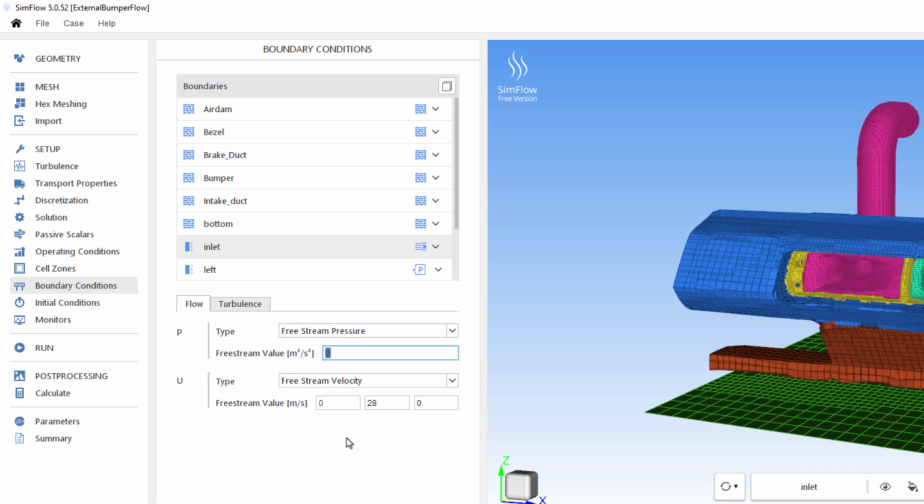On the pressure that would be built up on a bumper based on that amount of pressure approximately equals 127. So that's where these numbers are coming from. I'm not just pulling them out of the air, but that's essentially where these two numbers are coming from. Looking at driving about 55 or 60 miles an hour, what does the pressure built up on the front of a car, on the front of a bumper look like? Because this is my assumption. That's what's going to happen, is this area will be pressurized, and then the flow, essentially the speed of the air, and that's how we come up with these boundary conditions.